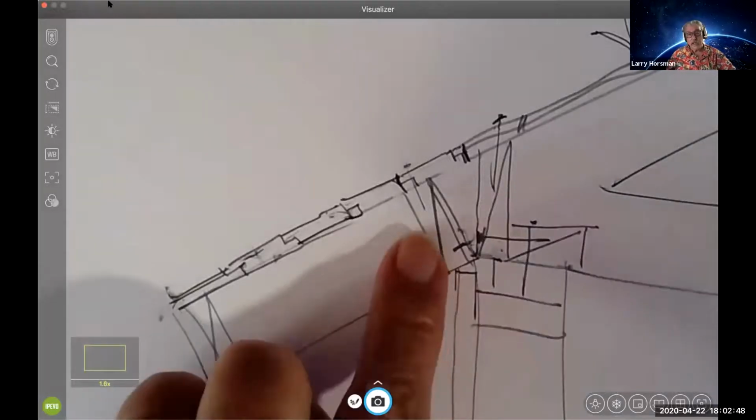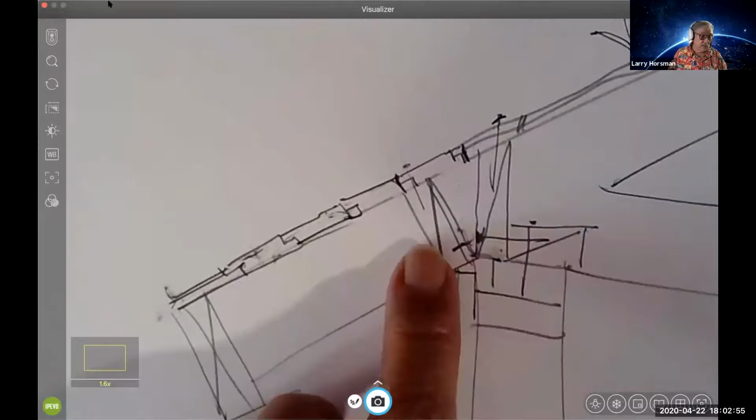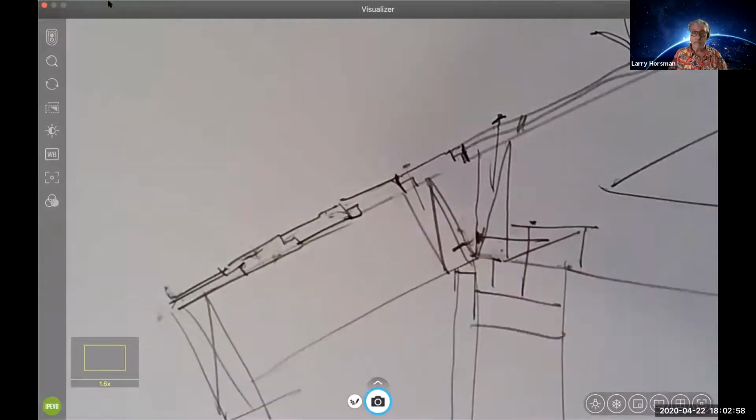If that's installed, then you can't face nail directly into it, but a lot of times this gets put in after the fact. Now you've got twice the labor for the blocking. Now you can use an ACX to it, and that A-face is considered to be paintable. But again, it may not meet the very high fire hazard areas, so that'd be something that would show up either as an RFI or something else.